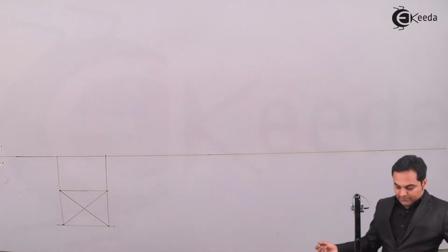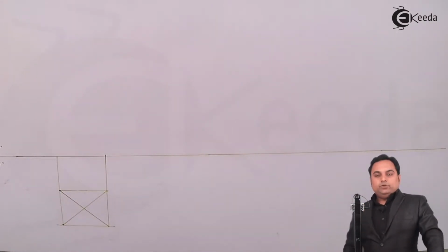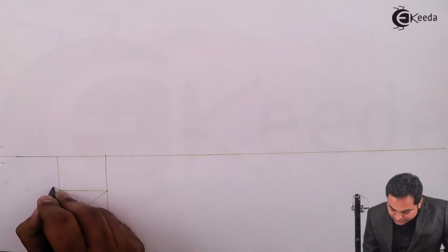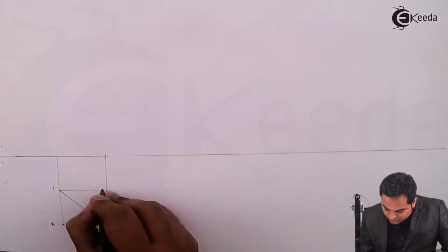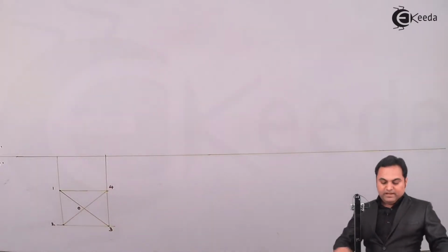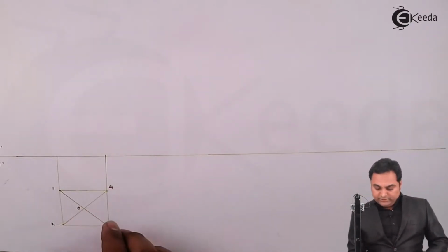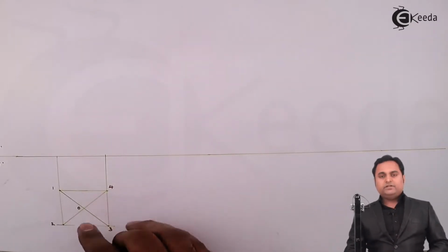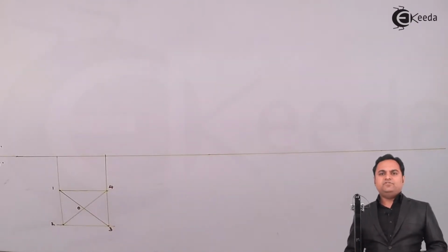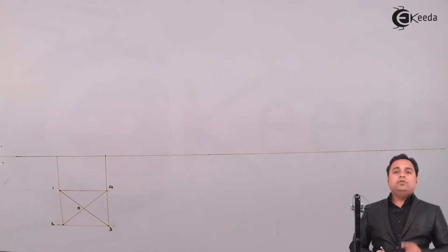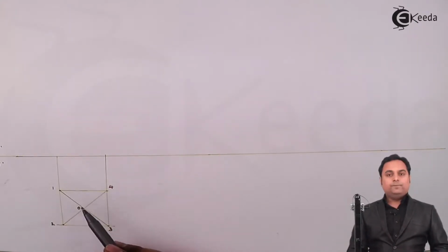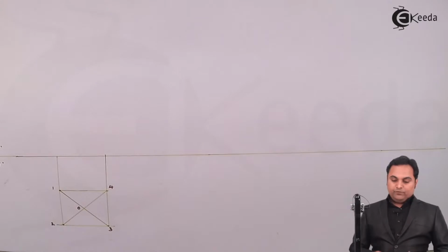So this is the square pyramid as we look from the top. Here I'll give the notations. Now I used this condition because only in this condition can we tilt the pyramid so that it will rest on the triangular face as mentioned in the question, and that triangular face is O34. So this is the top view of the square pyramid.